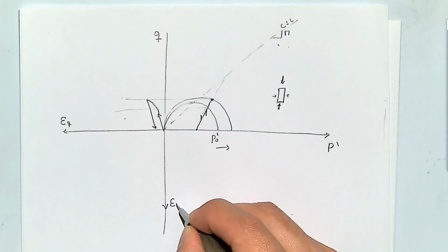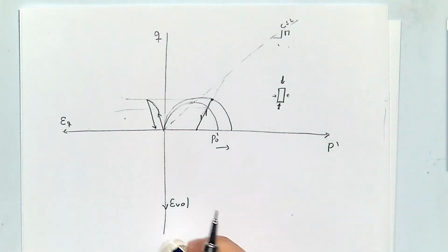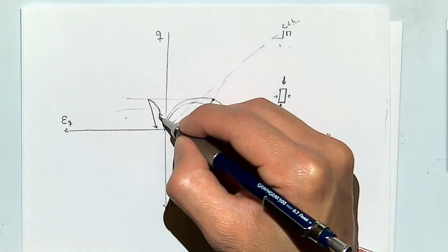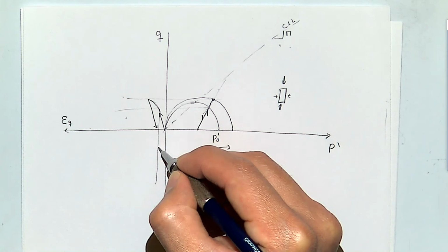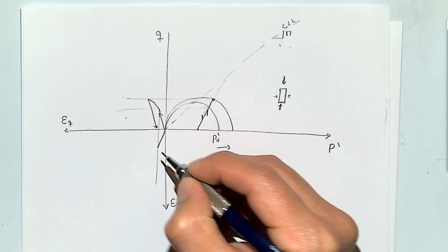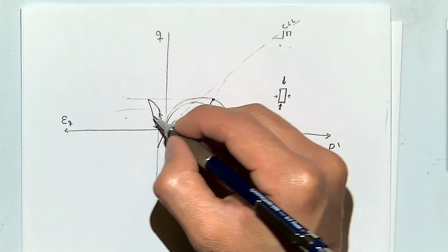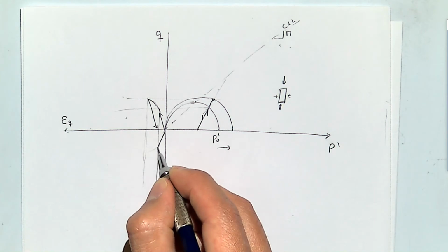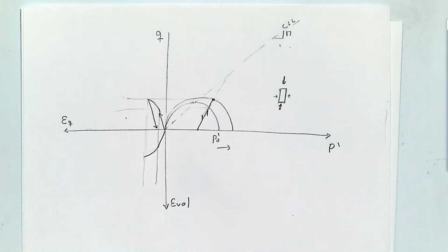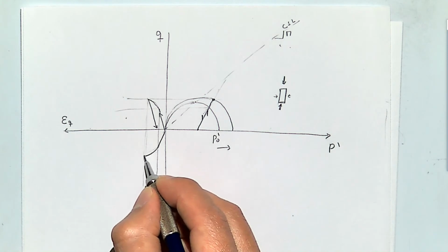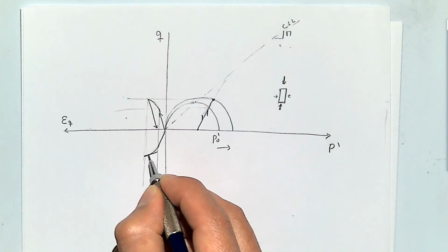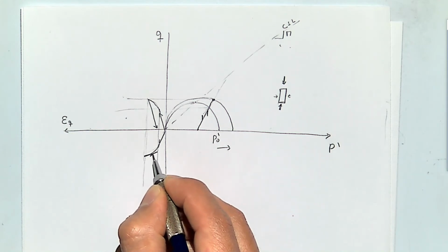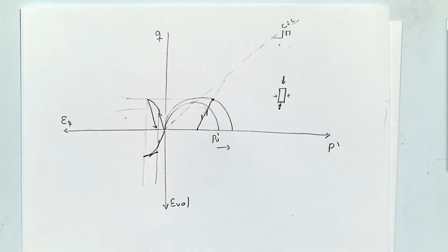If we look at the volumetric component, the rock compacts. It gets to the yield point somewhere over here, and it starts compacting more, and we will not recover all of that volumetric strain, and we get to a point over here.